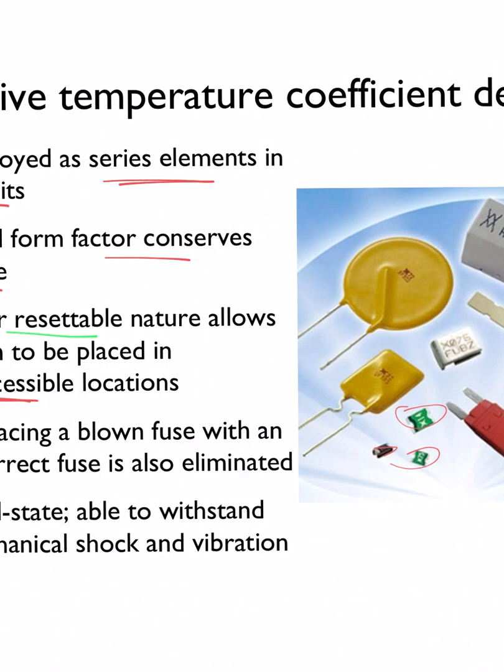If the engine overheats in the right location, one of these things will trip. And because they don't blow at all, you don't have to worry about replacing it with a wrong fuse, which used to happen a lot. You put a 30 amp fuse in a 15 amp fuse spot, and that's a recipe for a fire. And as kind of a bonus, they're solid state. Unlike what we still see with fuses in boats and cars, it's just a little skinny piece of metal wire, all right, that can vibrate, or sometimes a spring. And these are not that. They're able to withstand mechanical shock and vibration.